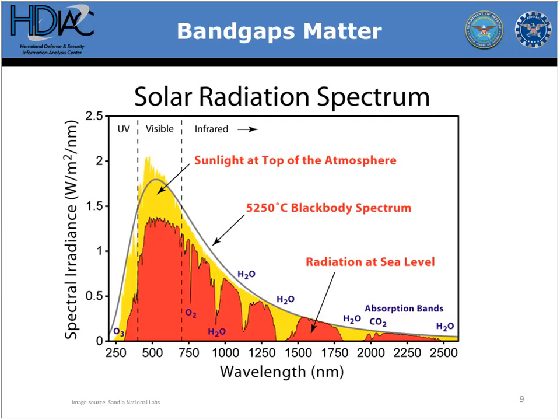But any excess energy greater than the band gap is wasted. You only get as much energy as the band gap. And so it's a fundamental trade-off central to PV design. Low band gap gets you large electron numbers, but a high band gap gets you higher voltage per electron, more bang for the buck, you could say. As I said, this trade-off is central, and it imposes some limitations on the max efficiency we can get out of classical PV cells.